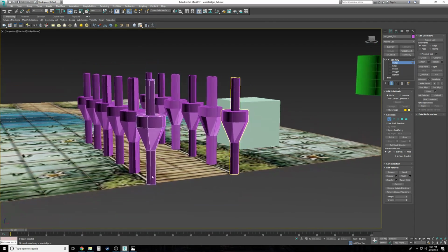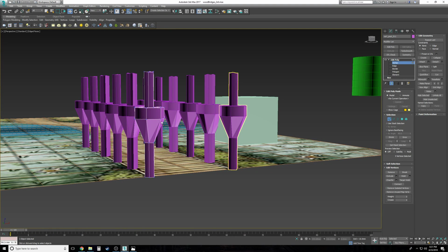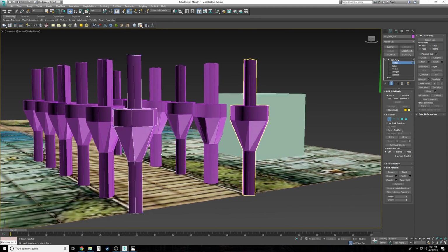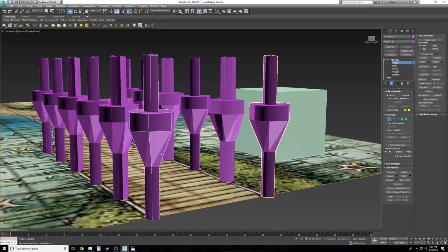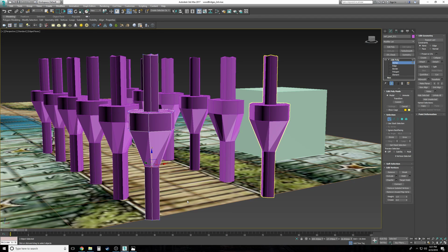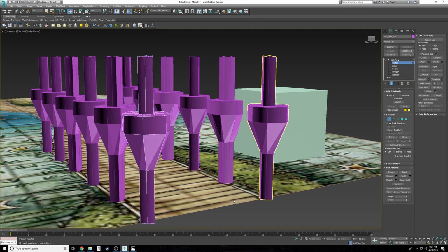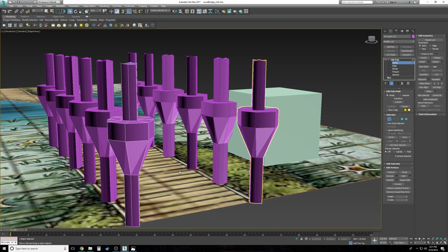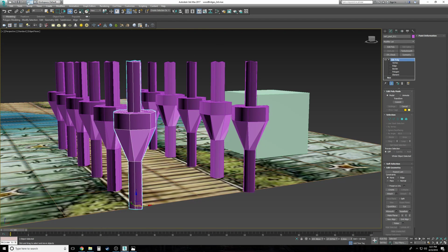So this is going to be good because now it prints, and it should be high enough of a vertical that it'll just make circles around and around and around itself and not need supports. When you go into your slicer program to experiment and see the supports before you print, if there's a whole bunch of supports here, that means it's not sharp enough, and you need to bring this down even farther, way down there, like that, until it comes to a point where you can print it without supports. But these should not have to have supports at all. So that's good. Let's save real quick.